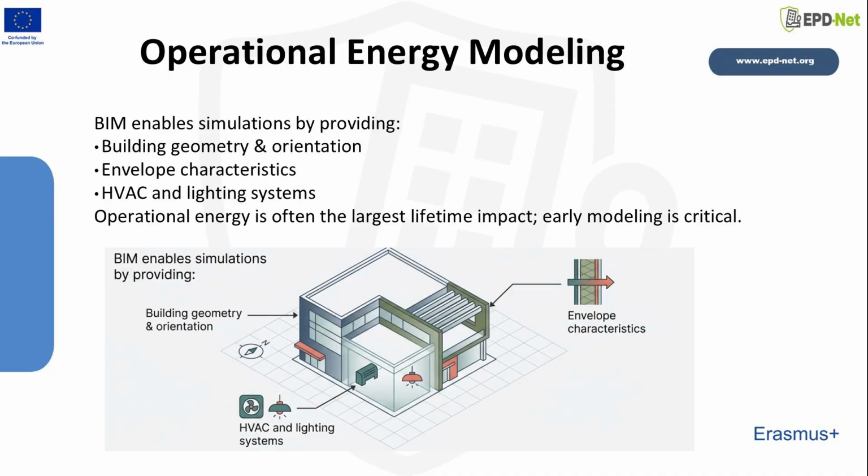Operational energy calculations focus on the building's performance during use, typically covering heating, cooling, lighting, and ventilation. BIM supports these calculations by supplying geometry, surface characteristics, shading structures, and HVAC system layouts. Simulation engines such as EnergyPlus and DOE-2 connect to BIM models through export workflows or plugins.